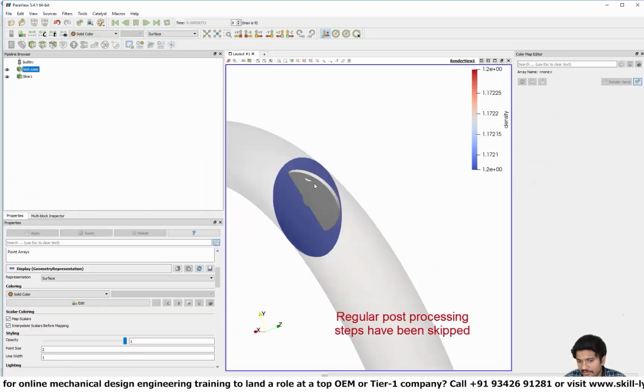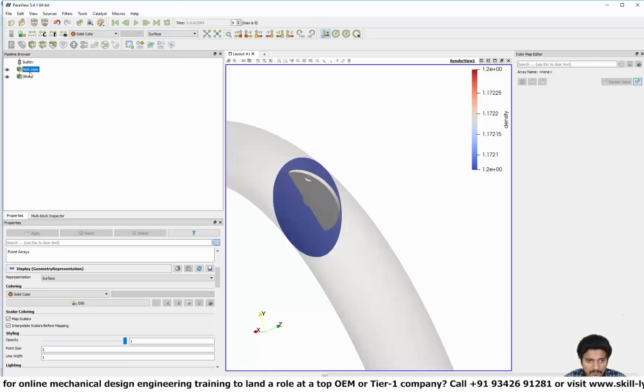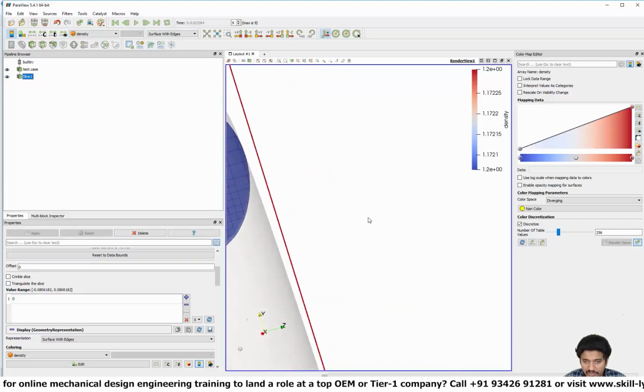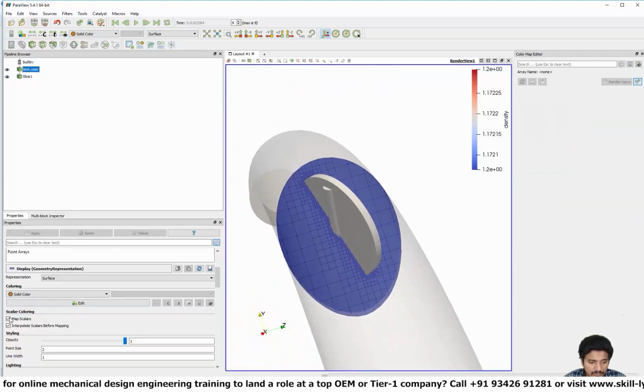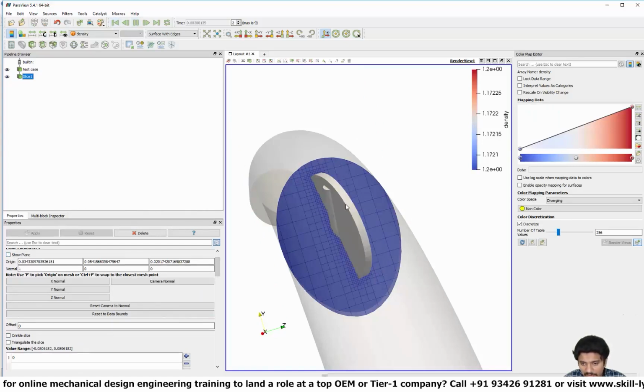In 2 milliseconds it reaches that particular value and then it stays there. And if you make the mesh, and then if you select your slice and then just display the mesh, and then just click on triangulate the slice or uncheck it, you can see how your mesh is getting created. So this is the beauty of cut cell Cartesian method. The mesh generation process is quite easy, and you can see that the mesh automatically moves, and when the mesh moves, the embedding also moves.